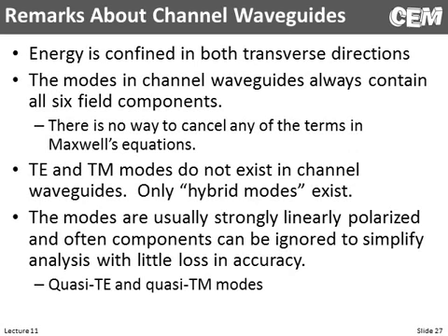So what we're going to do is, rather than call them TE and TM, we're going to call them quasi-TE and quasi-TM, just to remind us it's an approximation, it's not a real physical thing. Channel waveguides don't support TE and TM modes. They only support what we call hybrid modes, which really just means they have all 6 field components.